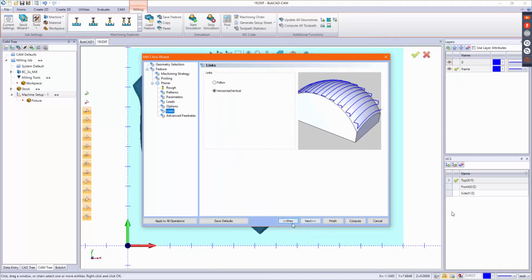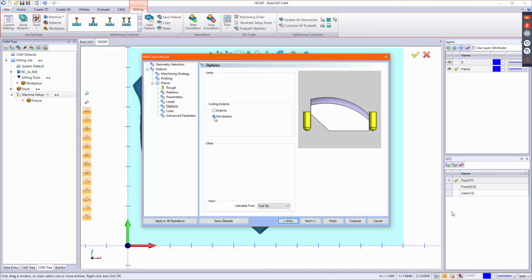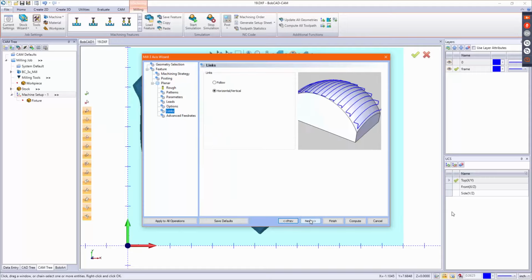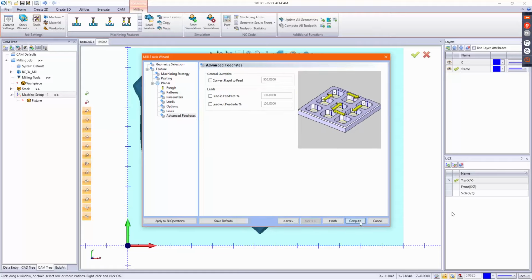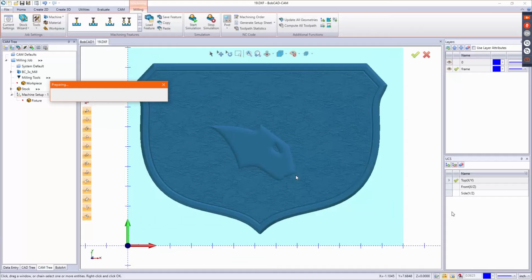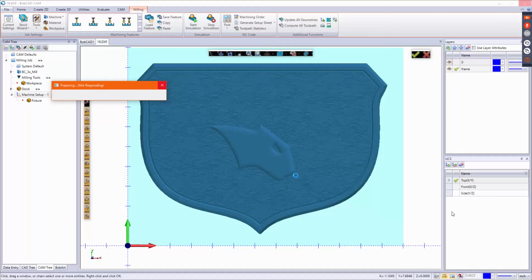And we really don't need the rest here. Let's actually take it to part bottom. I want it to go all the way to the bottom of the edge of the part. And we'll have it follow surfaces. And I think once this calculates, I'm going to go ahead and save this one, just so I can make sure we don't lose anything up to this point.